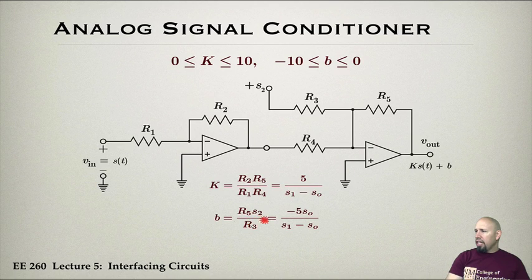Okay, then I can choose R3 to make this, and so forth. In other words, we can choose a resistor. So R1 and R2 to make this happen. Since I have one equation and 2 unknowns, I would choose, for example, R1 to be 10 kiloohms, and let's say make these two guys 10 kiloohms. So all of these are like 10 kiloohms, and then R2 is going to be this times 10 kiloohms, and that's what we would choose as the value.